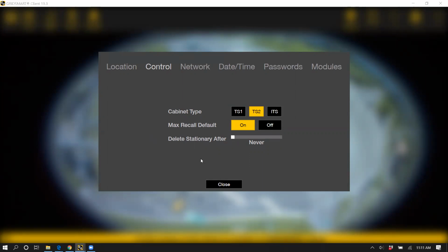Delete stationary is a primary function for maybe streets where you have multi-use lanes where they can be parking sometimes of the day, and a through or a right-hand turn lane at other times of the day. So what this would do is, for vehicles that are parked on the side of the road during the parking time, you can set a time limit. When that vehicle is stationary after 3 minutes, that vehicle then sinks into the background and the system would ignore it, so it wouldn't put in calls. That would probably be the primary use case of that function.